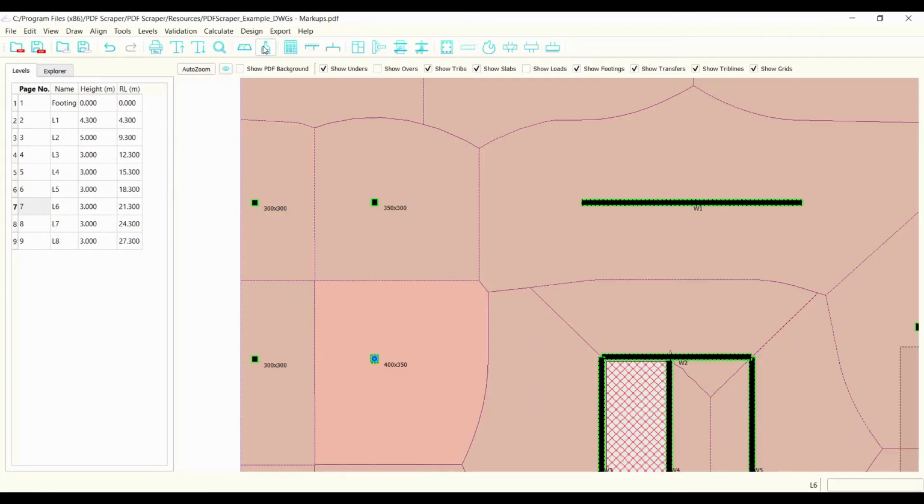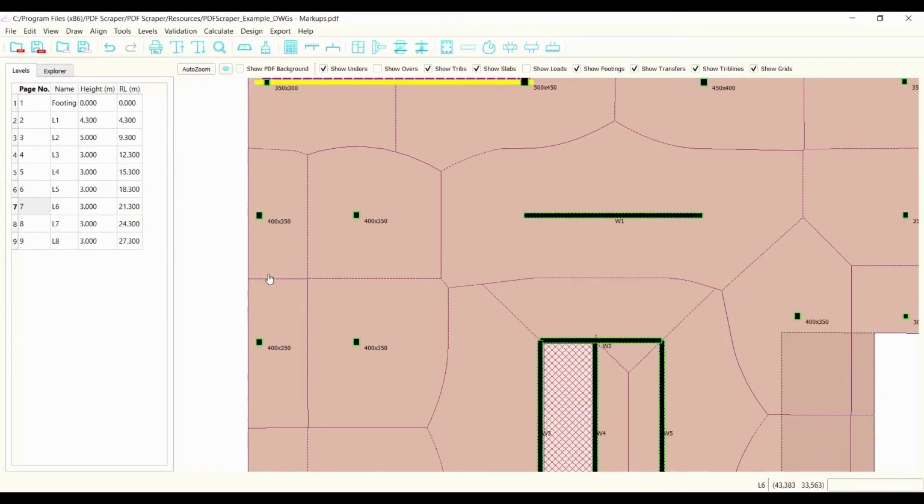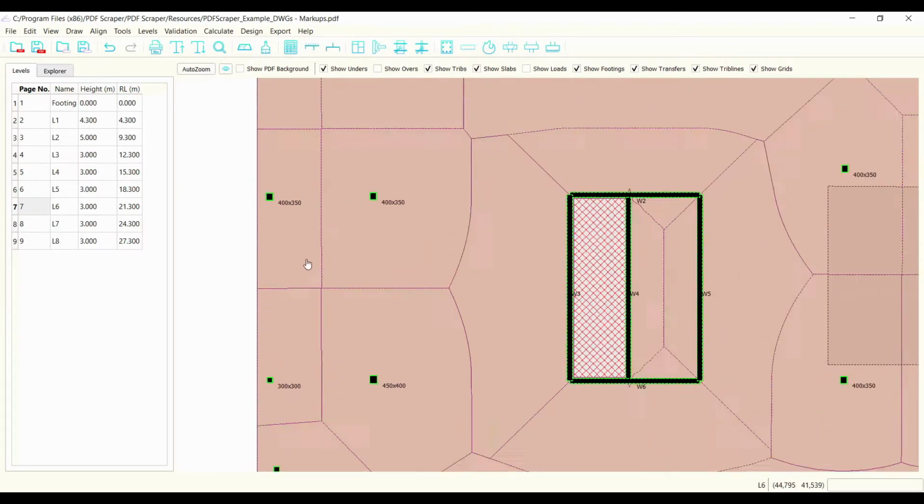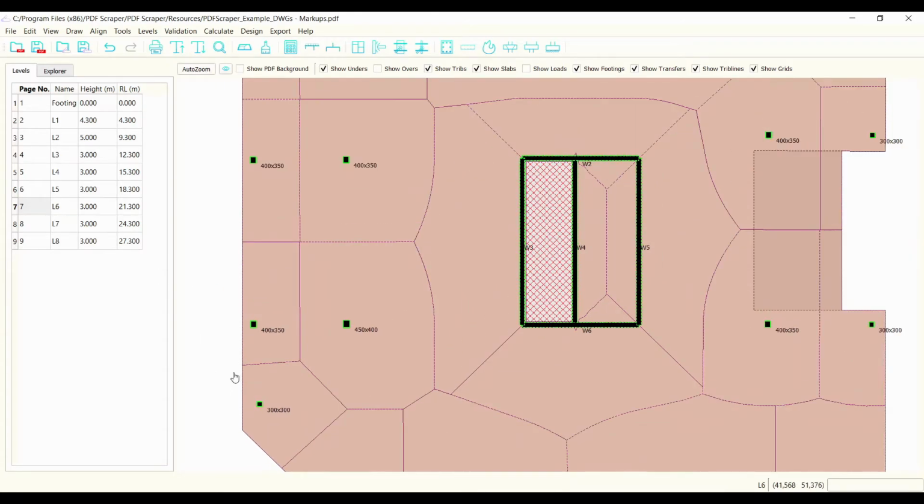So I can select that. I'm going to select the Format Painter here, and then all I need to do is just go and click on these columns, and it'll just paste the format of that column, so the size and some of its parameters, to the cell we're clicking on. And we can do that just to rationalize the column sizes on a particular level a bit.